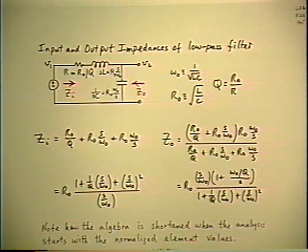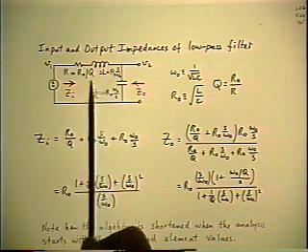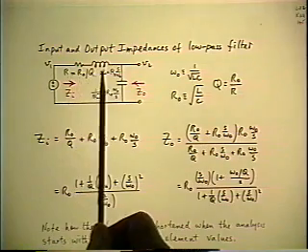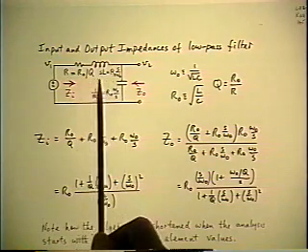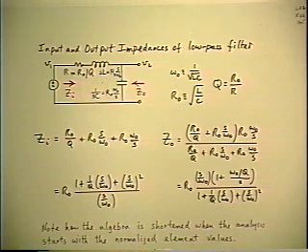So if we want to calculate different transfer functions, it's a reasonable assumption at the beginning that we're going to want the same normalized quantities in the answer. So we'll save some work by anticipating that, and before we write any equation at all for the new functions, let's get rid of the original circuit elements in the model and replace them in terms of the normalized quantities that we know we want in the answer.